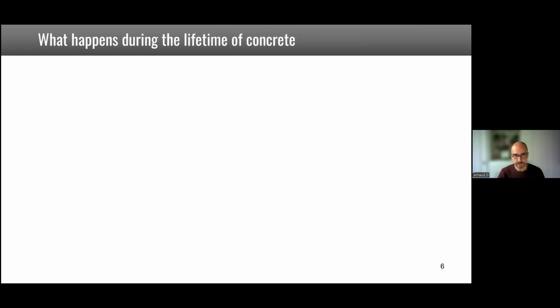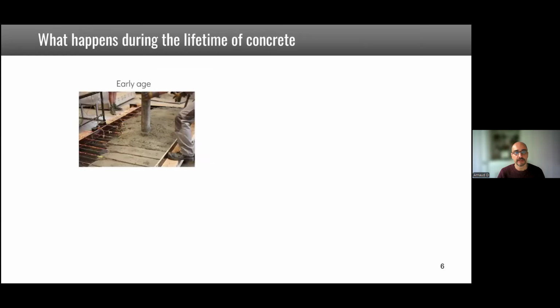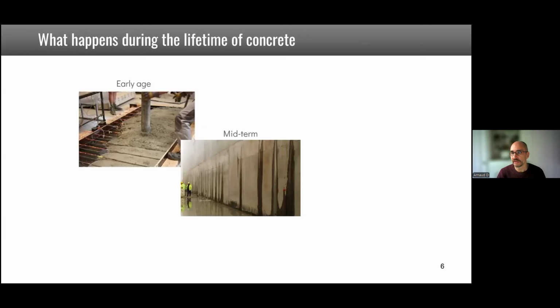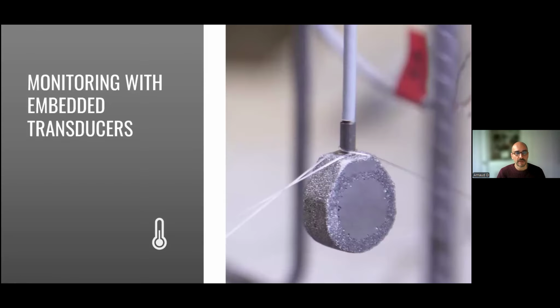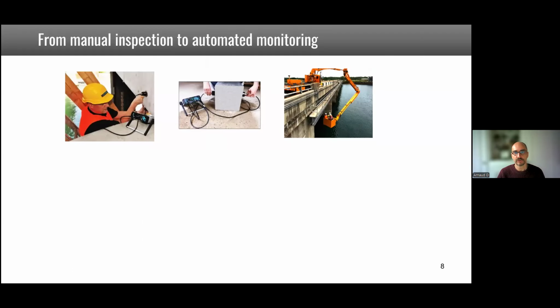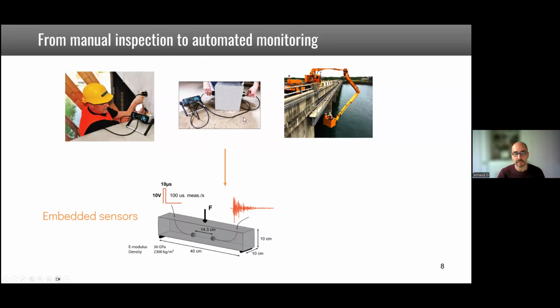Okay. And then during the lifetime of concrete, we can use these kinds of wave propagation to detect what's going on at early age and even for the long term. But in my research team, we've been focusing for more than 15 years now on using embedded transducers. So the idea is to avoid having someone coming here and having to have access to the surfaces of concrete to do the monitoring, by using embedded sensors.